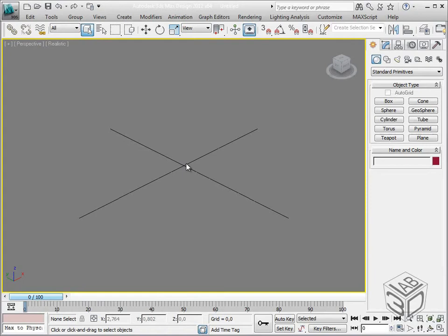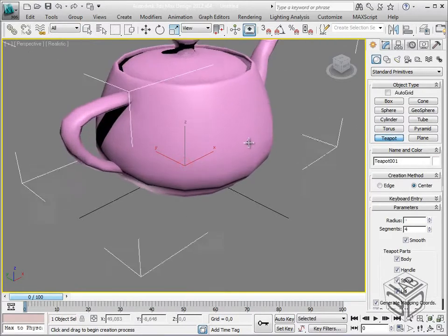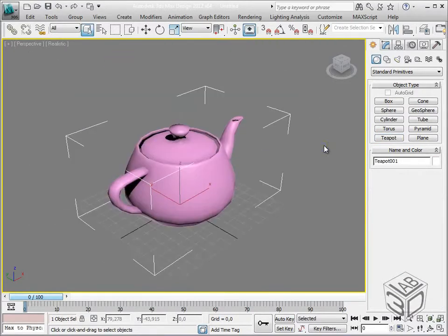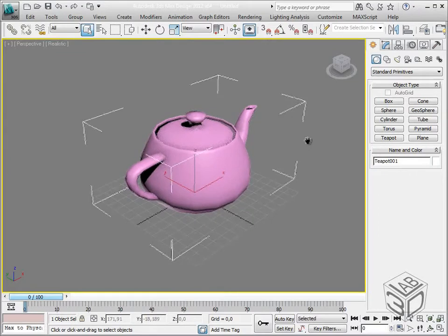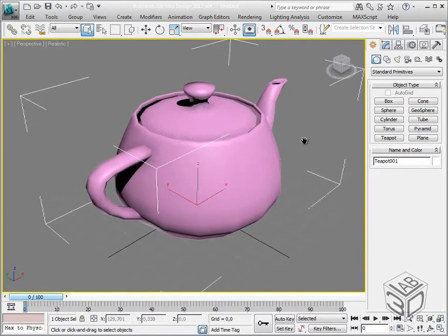Let's see now the steering wheel tools, used for efficient surfing inside the working windows just with the mouse. Create first a referring object. I center it inside the view with the Z button, and through the pan of the scrolling ball I move it to a better view.